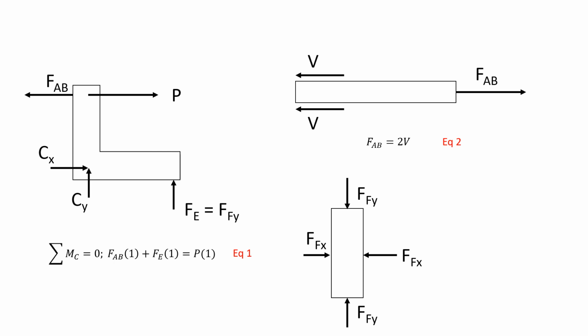The bar will be compressed, so the length would decrease, and then it would thicken along the x-axis. So the walls will prevent the elongation along the x-axis, hence your compressive force X.